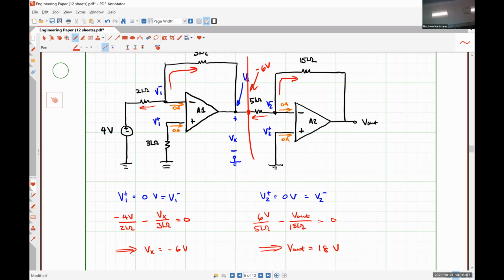Yeah, on the exams, if you look on the old exam 3s or whatever, the only thing I ever ask is what's the voltage present at either the inverting input terminal or the non-inverting input terminal. And if you can solve for one, you get the other. Solve for V plus, and V minus has to be equal to that. And then I'll ask for what the output voltage is. That's it. In circuits 2, I start getting a little bit more wild asking things because we're not dealing with simple negative feedback circuits. But the only really thing that I might ask, even of a circuits 2 student, specifically an electrical engineering major, might be, well, what's the current that's leaving the output terminal of the op amp? And we can figure that out pretty easily just using Kirchhoff's current law again.